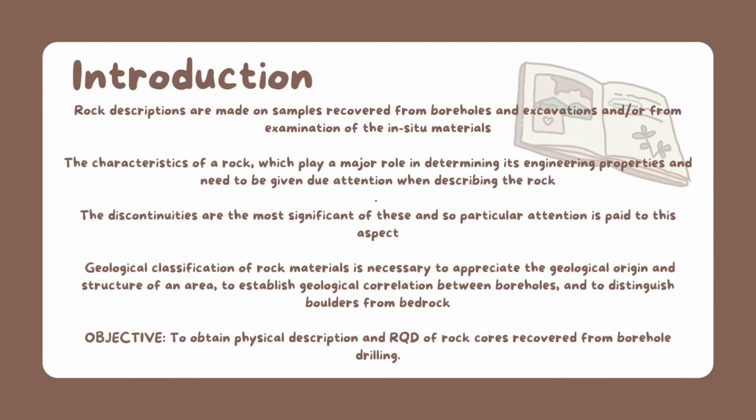First of all, rock descriptions are made on samples recovered from boreholes and excavations or from examination of the in-situ materials. The characteristics of a rock which play a major role in determining its engineering properties and need to be given due attention when describing the rock are the strength, weathering effects, and the discontinuities. The discontinuities are the most significant of these, and so particular attention is paid to this aspect.